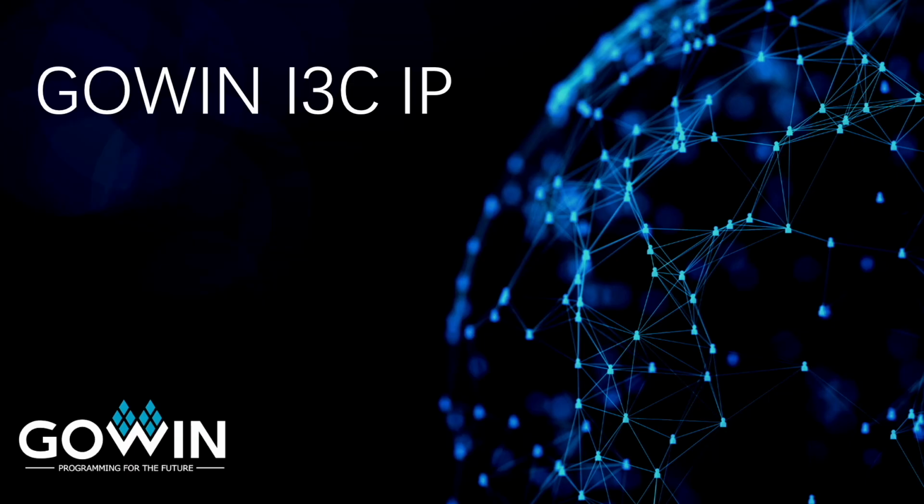Now let's focus on GOWIN's I3C IP offerings. In the GOWIN EDA tool, when you open up the IP core generator, you will find three different flavors of I3C IPs: I3C Master Slave Combo IP, I3C Master Only IP, and I3C Slave Only IP.